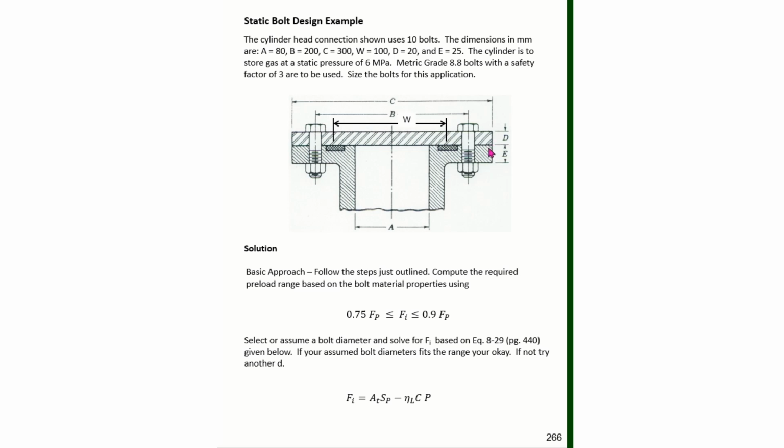E here, the thickness of the cylinder head part, is 25. We know the internal pressure is static at a magnitude of 6 megapascals. And we're to use metric grade 8.8 bolts with a safety factor of 3. And we need to size the bolts for this application.